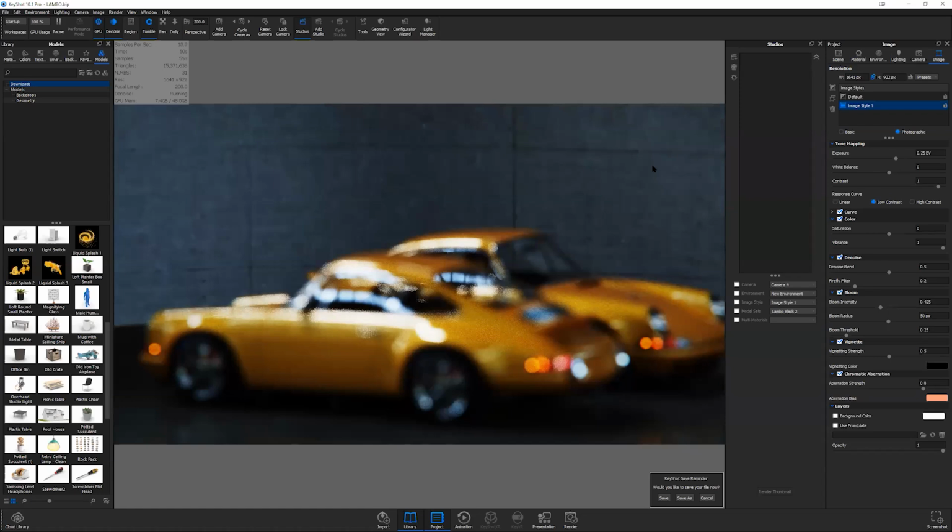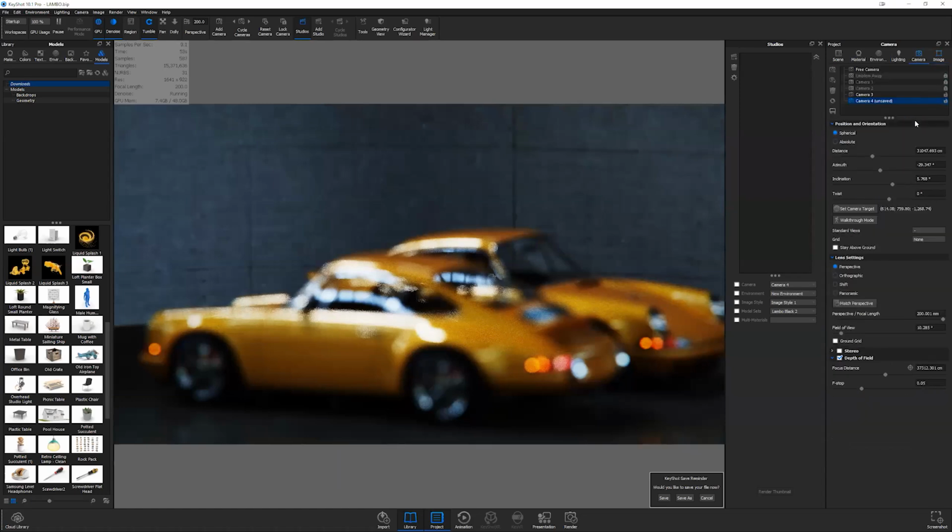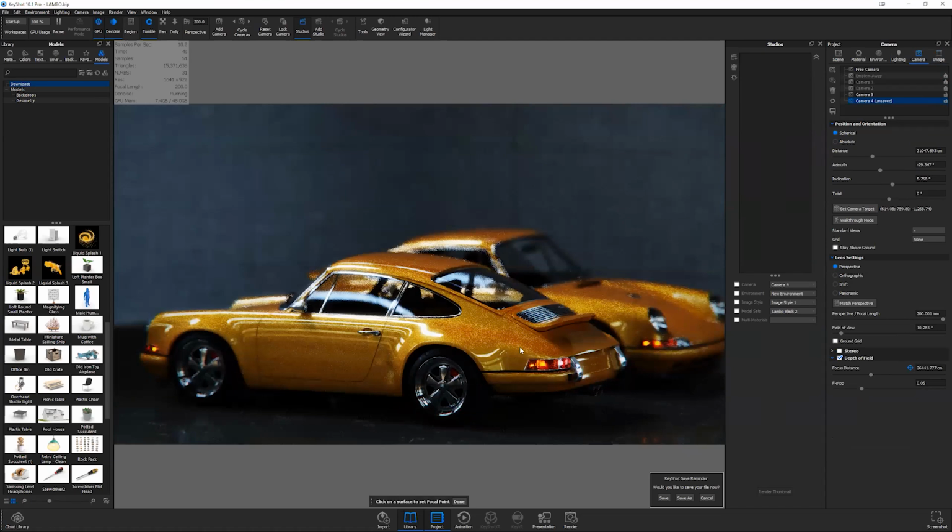And of course, there's often a time where a decision or a part is being changed later on in the process, almost close to the product being printed on the package. At that stage, it's as simple as going back into SolidWorks, updating the model, importing it back into the file, and re-rendering. We have all the assets set up. We know what our materials are going to be. Everything's already set up. So it's as quick as rendering that out, putting it into our Photoshop file, going through that breakdown process again, replacing the TIFF file prior to it going into the Illustrator file, and then just knocking it out.